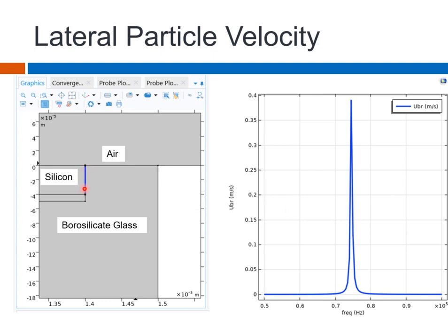The boundary condition is that the silicon plate over here is fixed. It is bonded to the borosilicate glass. So this is again a 2D symmetric axis, 2D symmetric model built in COMSOL, which has a borosilicate glass at the backing. It is 0.5 mm thickness. It is like 500 microns over here. You can see the scale. And this silicon plate is about 40 microns, as I've been telling before. And the cavity is not too deep; they are shallow. So that is about 10 microns over here.